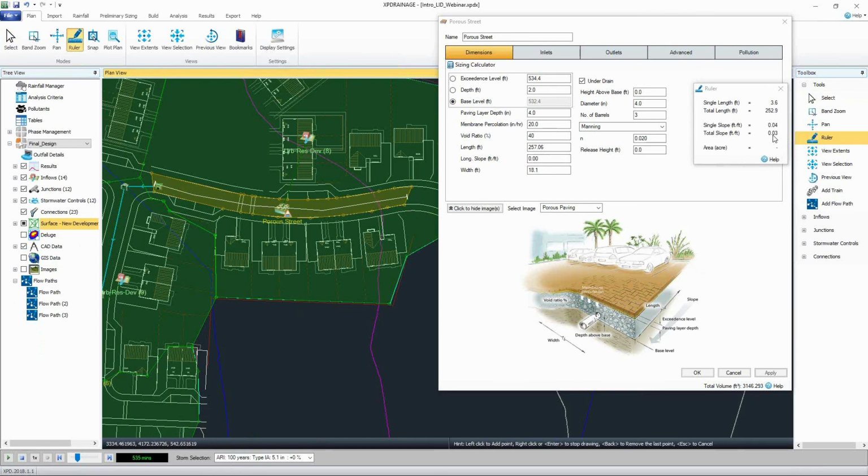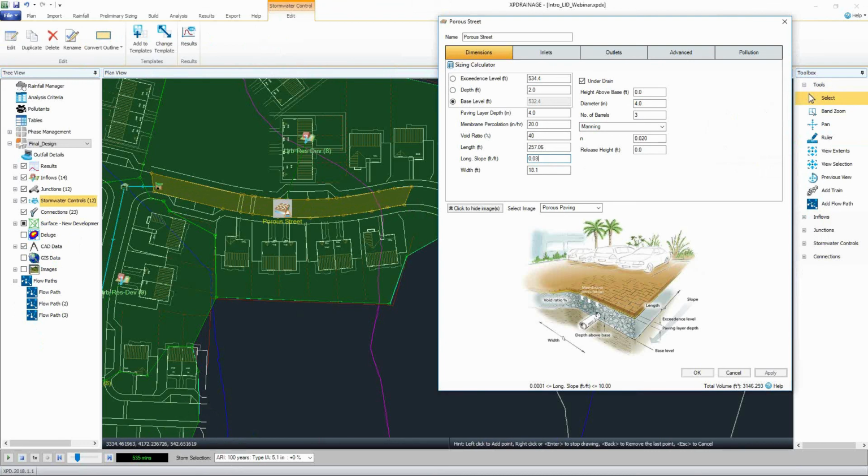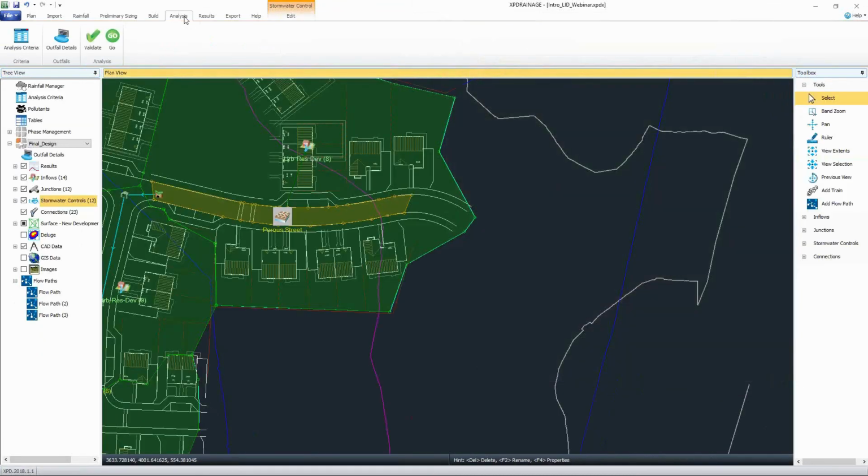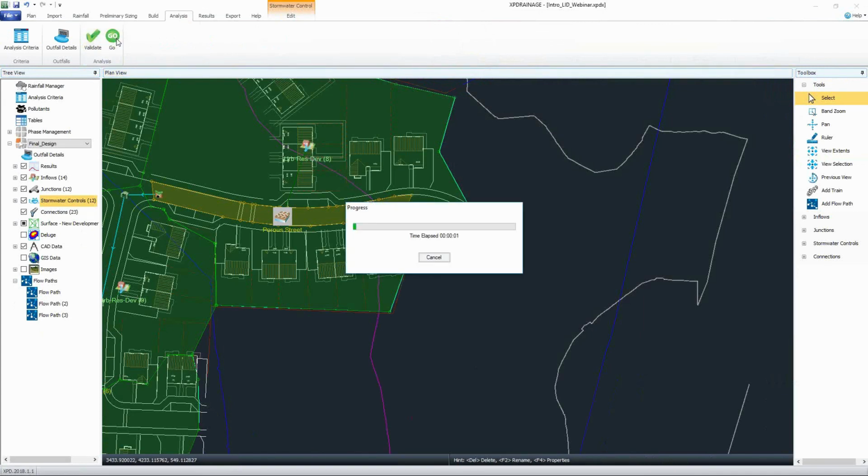So we'll see here, we got about a 3% slope, 0.03 feet over feet. Well, I should probably change that. So all right, say that's 0.03, and I can just run this assessment again. This is going to run a whole range of rainfall events and different design ideas that I have. So I'll run this again, and we can look at the exact same thing.